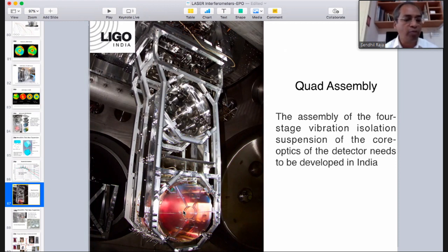Just before the pump down, this pink coating is peeled off. It's a very special polymer called first contact, which peels off atomically clean, taking away any residual dust from the coating. So the coating is a dielectric coating. If you make a dielectric coating at 1 micron, it will be almost transparent to the visible, except for a few visible tinges, which are because of high frequency reflections also.